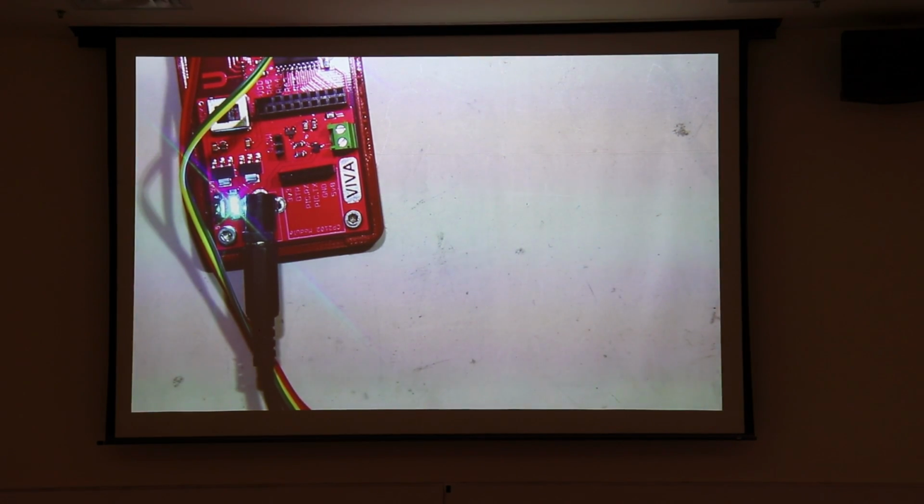So why do we need pull-ups? We don't put pull-ups on our other lines, right? Well, we do on our inputs, but normally our lines are driven. It's either high or low when we're using it as an output, right? So how come I put pull-ups on there? Does anybody remember? Somebody was going to take a whack at it? All right. So we call it open collector.